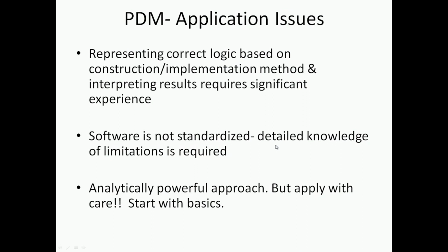Okay, so unless you really have a lot of experience and you are able to represent the logic of the construction method that is going to be used very accurately in the PDM, it is not advisable to use these complex relationships when you are starting out in your planning exercise.